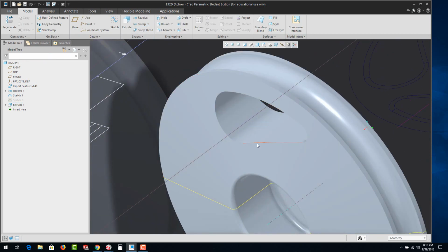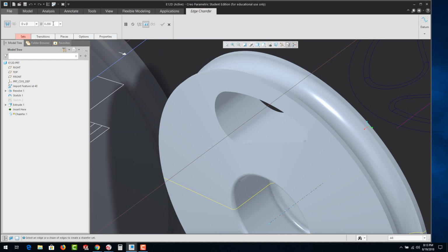Okay, now there's little chamfers of 0.125 on here. And again, if you need to, you could open up the drawing, and I believe those dimensions are in there. But if I recall correctly, this is a 0.125. And we're going to leave it distance to distance, which if it's at 90 degrees, leaves it at 45. Or you could set it to 45.